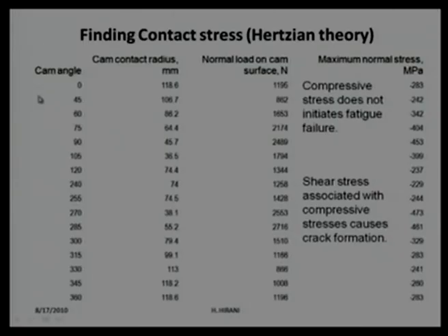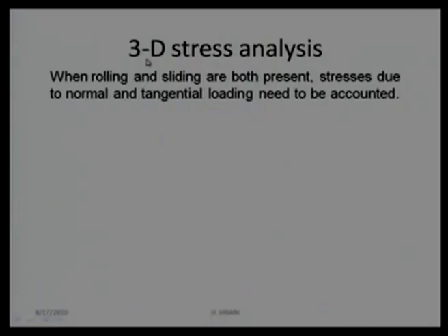So what I am trying to conclude from this slide is that Hertz theory is not sufficient to explain pitting wear. First, we need to find the associated shear stresses generated at the subsurface, within the surface. In addition, if sliding is introduced, how the shear stress moves up, shifts toward the surface, and also increases in magnitude. For that purpose, we require a 3D stress analysis.